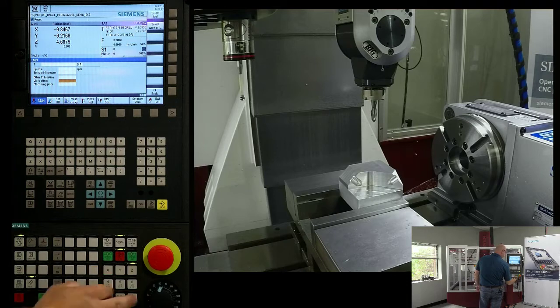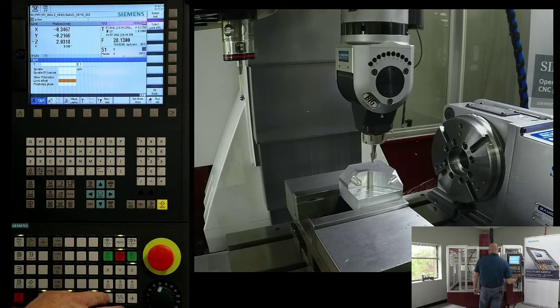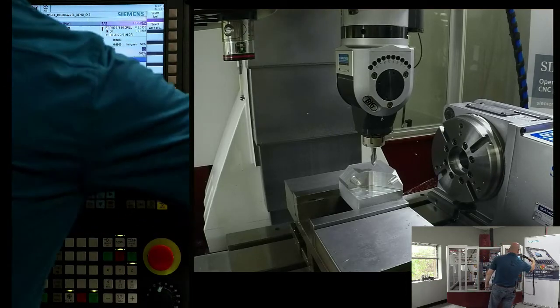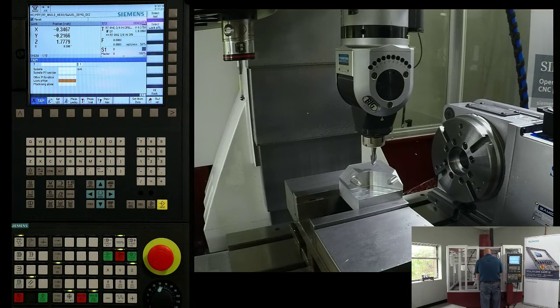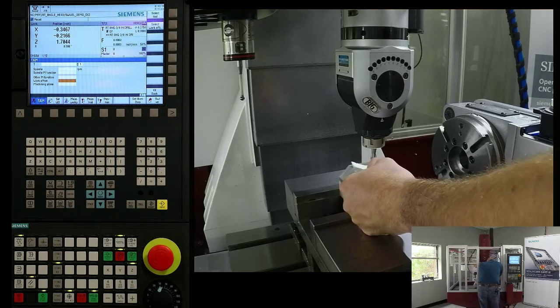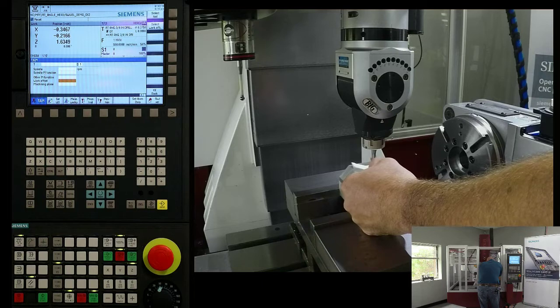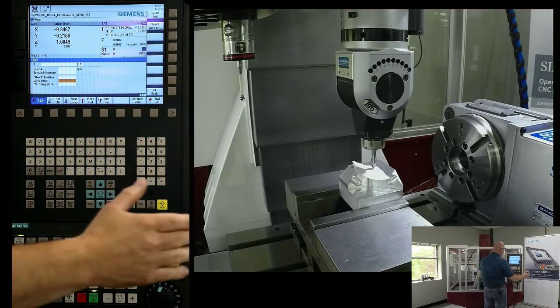We're going to bring our Z down, get it kind of close. All right, so now I'm just going to use my hand wheel, move the machine down. I'm going to use the old paper trick here. It allows me to bring her down to a known datum. Certainly, I may want to do something a little more accurate depending on what kind of tolerances I'm trying to hit. For speed's sake, this is a quick, down and dirty method of touching off a tool. So I bring it down to my plane, and now I have to tell the machine to set the offset.